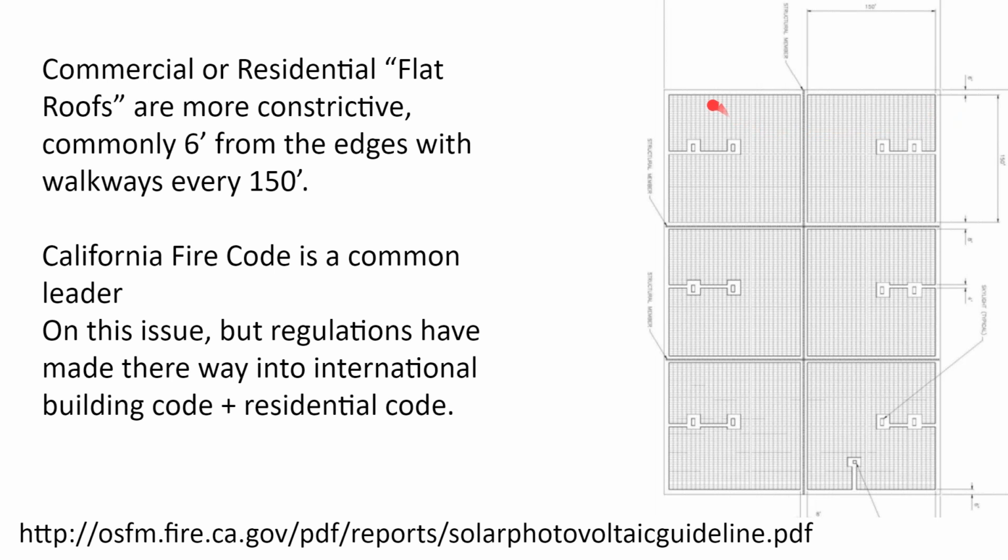On top of that, having a walkway every 150 feet, a lot of these are safety codes, and they're for your own good. And you're like, well, is that a little excessive to have an 8-foot walkway every 150 feet? Well, there have actually been a few solar fires that have burned down some commercial buildings. The big one was the Dietz-Watson fire in New Jersey. It happened a few years ago.